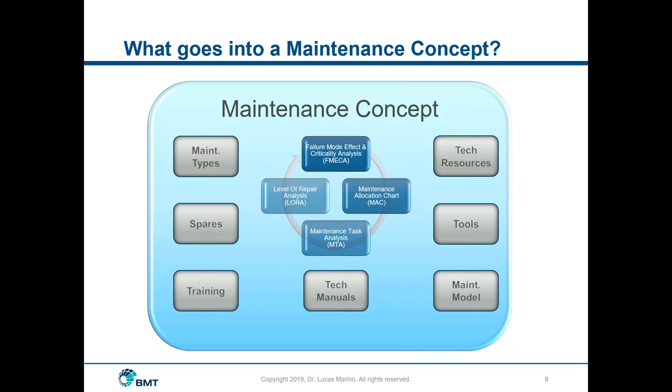So when we put those 4 analyses at the center of our maintenance concept, and we iteratively repeat this cycle every so often, which we can talk about the appropriate way to determine that time period. Really what you're doing is you're reaching outside of those analyses and you're impacting all the things that encompass a true maintenance concept. Your maintenance concept should address your technical resources, your maintenance types. Which types of maintenance are you going to address with your own technicians or external technicians? Your spares, right? Parts replenishment. In the military, we refer to it as provisioning.